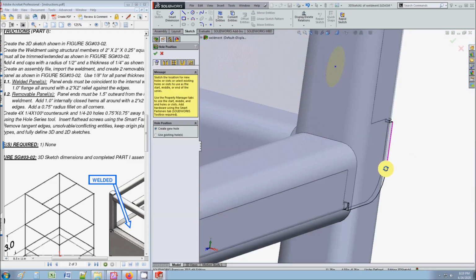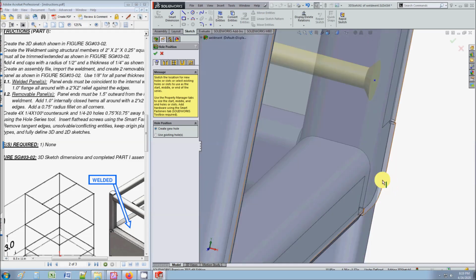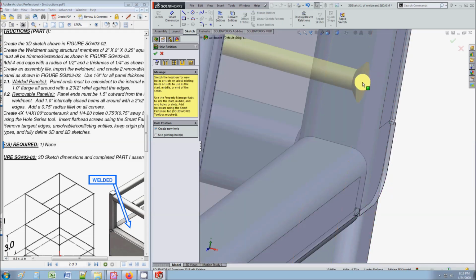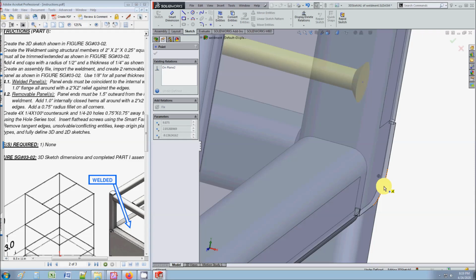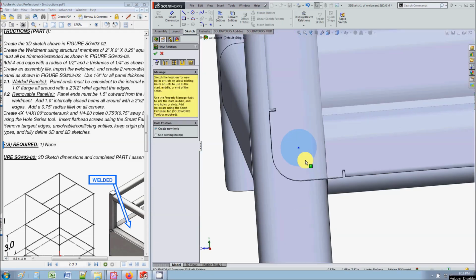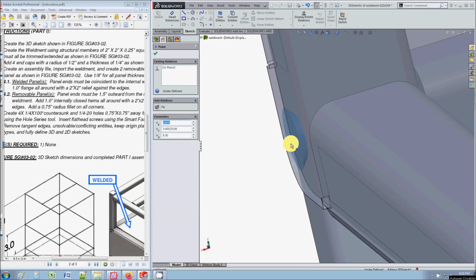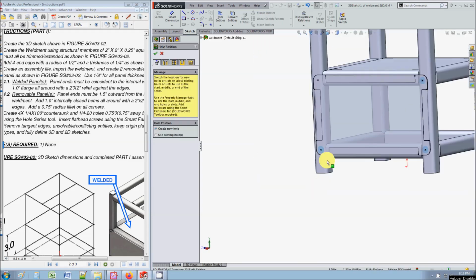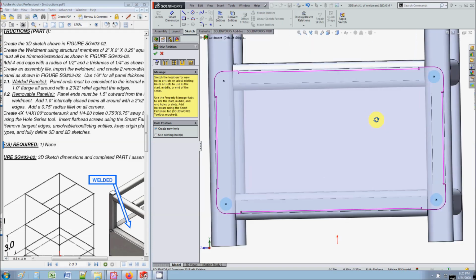So sometimes what you gotta do is rotate your mouse till there's nothing behind this fillet and move. So you hover over the edge and then it starts to show up. See that center starts to show up. Or you can do select other, that can also work. Okay, and I'm gonna do the same thing here. There, see? So that looks pretty good.